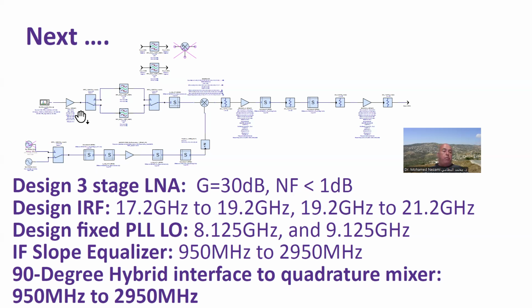They changed like 5 different companies, the same part though. One of the pHEMT devices that's used for K band, which has a noise figure F-min of like 0.8 dB. So I need to design a single stage, cascade 3 of them together, so that I can achieve this performance in here. The next thing I want to do then is this is the image rejection filter.